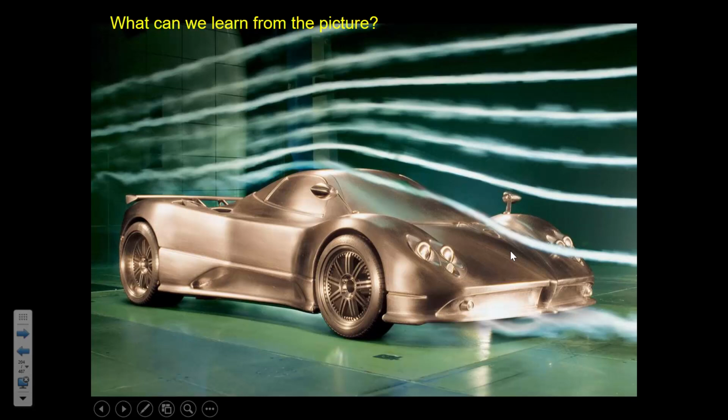We'll talk a lot more about that later next week when we talk about the Bernoulli equation in detail. But that's the general principle, and that's why airplanes can fly, is that on the top part of a wing the pressure is low, and the difference in pressure creates lift. So the difference in pressure enacted over an area, pressure times area, gives you a force. And so that's how there's equilibrium between the weight of the plane acting downward and the lift force, which is